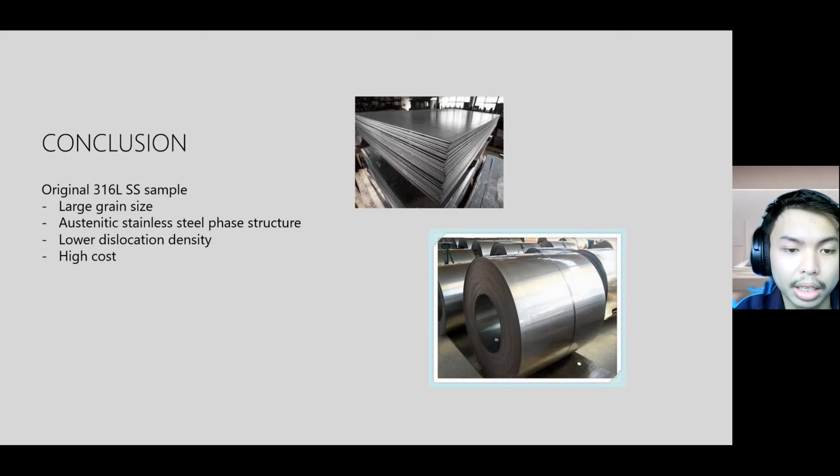The hardness and mechanical strength of the material increase, so we want to use 316L in a twin tower application. In order to improve its mechanical properties, we must cold roll it, and to further improve the resistance to residual stress, we can use heat treatment to improve the overall strength.